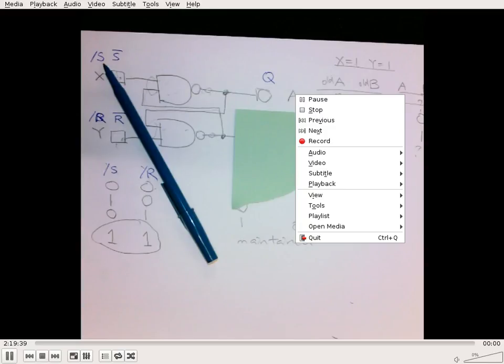So this is an active low signal. Normally this really big resistor, with a big value, is 10 kilo ohm, which is a very high resistance. So it has a very weak tendency to pull this particular line to VCC. But without any other mechanism in this particular setup, this line is going to experience VCC because nobody is going to tell it otherwise. Is that making any sense?